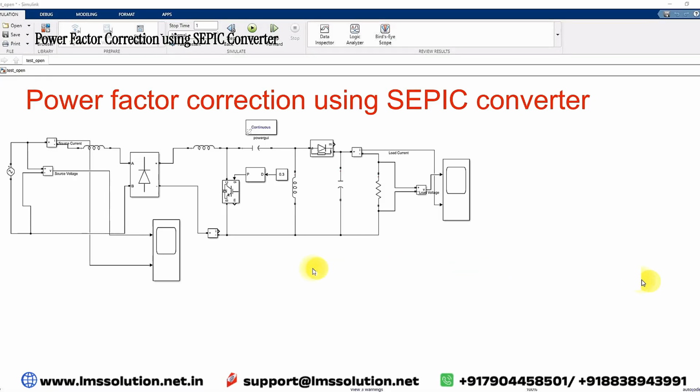This is a model for open loop control. It consists of source voltage, that means AC voltage, and diode bridge rectifier, and then this is known as SEPIC converter. This SEPIC converter is going to be controlled in the manner of open loop. Here we are going to provide 0.3 duty cycle, and here you can measure the source voltage and source current, and here you can measure the load voltage and load current.